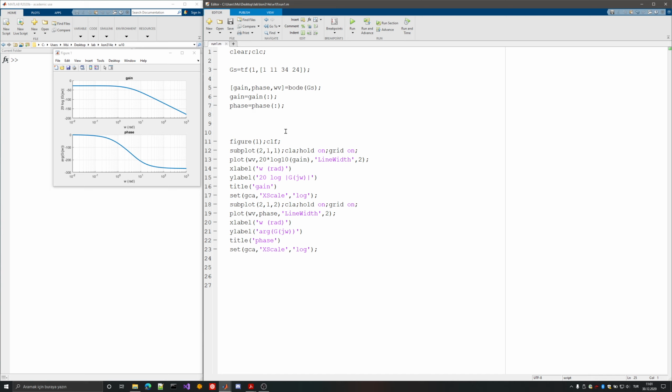So let's look for a unit feedback for starters. Let's assume that k is equal to 1. If that's the case, then my transfer function will be k times g divided by 1 plus this, and since k is equal to 1, it will be equal to just this expression, g divided by 1 plus g. Now, remember that we will be plugging in s equals j omega, and this is a complex valued function.